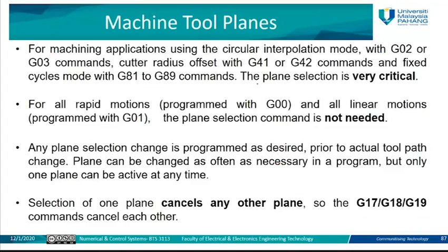Same here, the coordinates for the G02 and G03 clockwise and counterclockwise commands will be affected based on the commands G41, G42, G81, G89. You can refer to this place here.